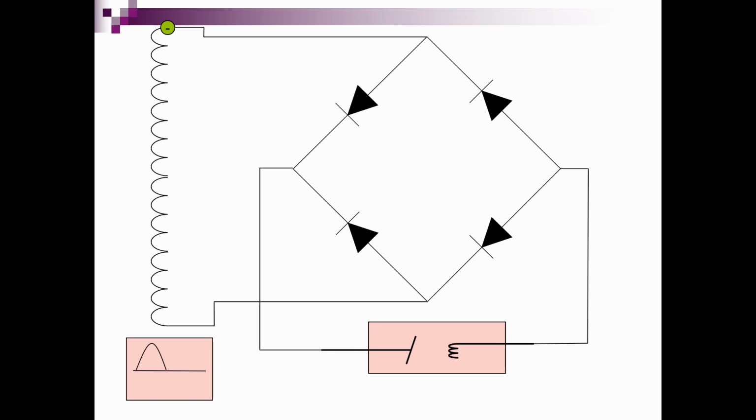The electrons leave the upper leg of the transformer and flow to the upper input of the bridge. At this point, the electrons have a choice. They will take the right branch because the diode at the left is blocking flow, while the diode to the right is conducting. Now the choice is between the cathode of the tube and the diode to the left. The tube cathode is hot and ready to conduct the flow of electrons, while the diode is blocking flow. The electrons accelerate across to the anode and produce X-rays.